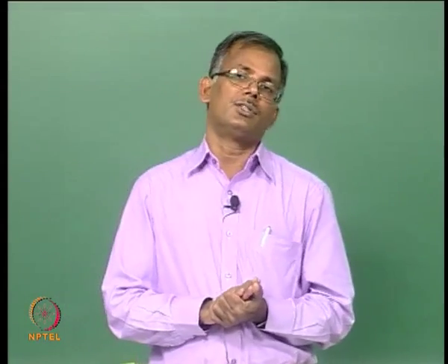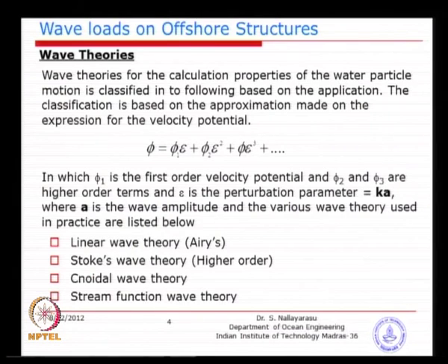We assume that the deflection is too small compared to the structure dimensions. So, when you do that, the geometry does not change during the course of response. How is that possible? That is exactly the situation here. The small amplitude wave theory, or linear wave theory, assumes that the surface is not changing or is too small to be visible. That is how the original wave theory was developed by Airy. Professor Airy developed this, which is very simple and very handy for computing loads on structures.